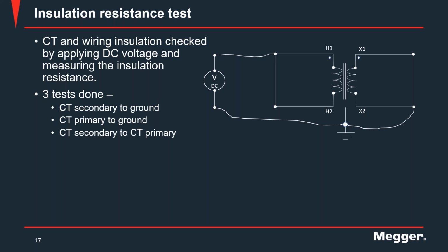Sure, and I should have explained this in my previous answer to the question on the nameplate. Yes, when you're using the nameplate estimation feature, you don't even have to tell the software whether the CT is metering or protection. The software will identify that for you. But again, I should emphasize, double check the results in the report if you're using the nameplate estimation.